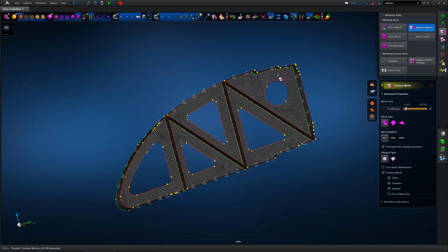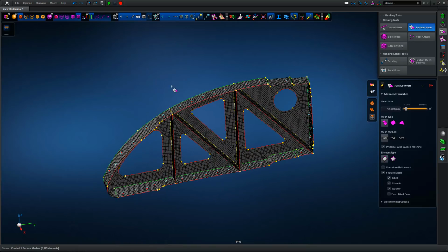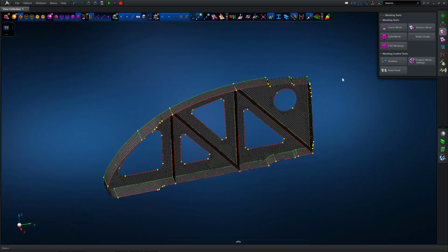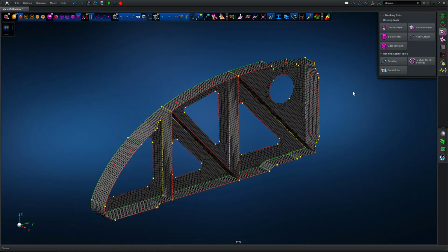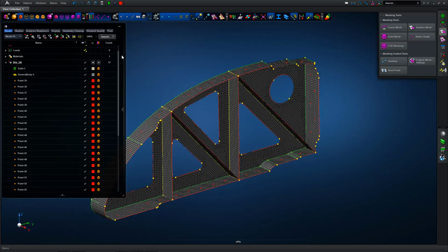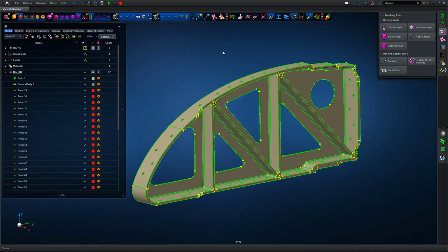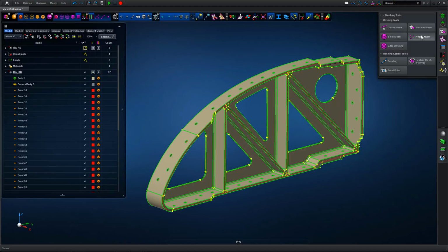So we've got nice regular squares at all the fastener positions. And then we perhaps might go back to the auto mixed tri and quad paved mesh for the underlying regions, just to get some local mesh uniformity where we don't have discrete fastener or hardpoint definitions. So that's the mesh completed.